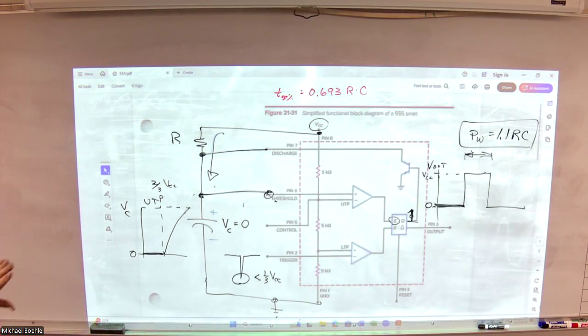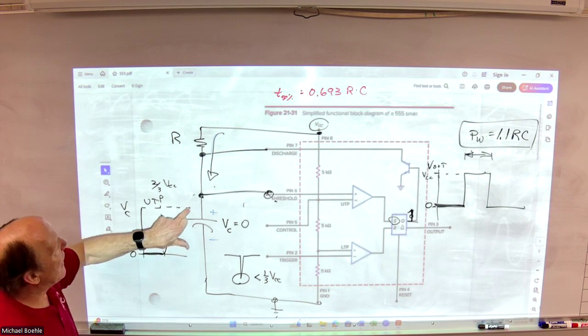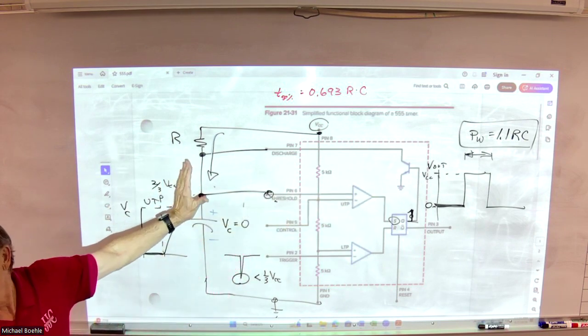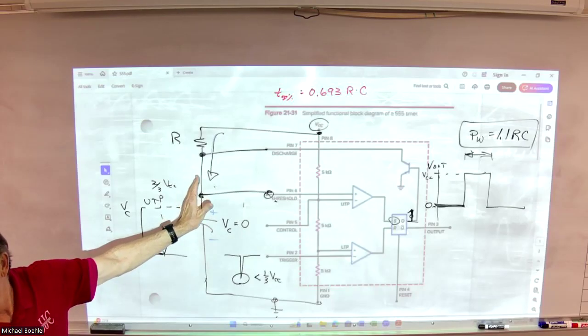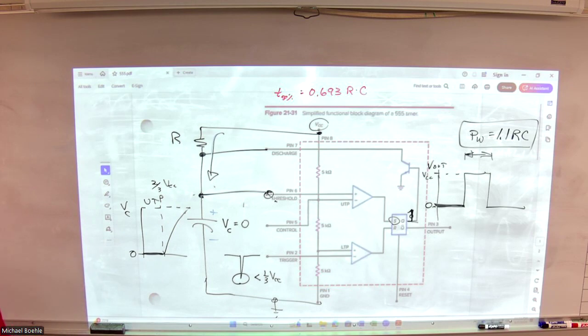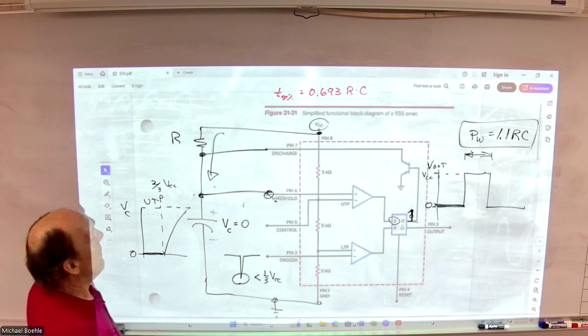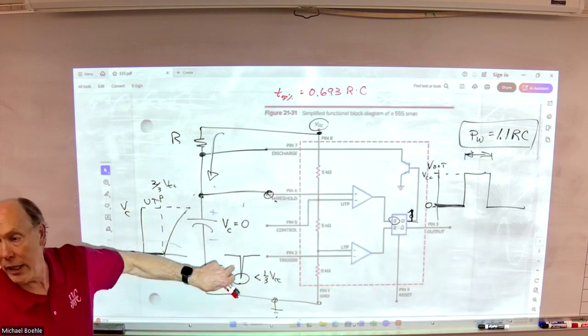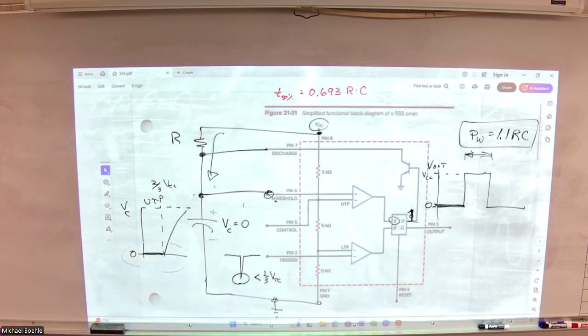And of course, what we see too is that when we trigger that, this transistor turns on. There's no resistor in here to limit the rate at which I discharge the capacitor. So it's a very quick response, very quick recovery, so that I'm very quickly back ready to start that process again as soon as I have another trigger.